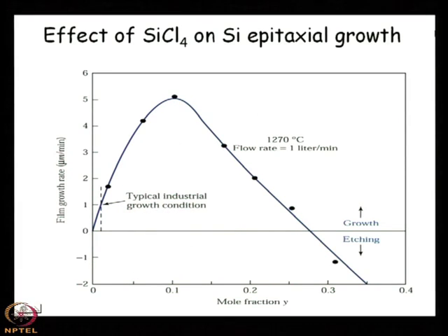So, the costing will be very, very high, because all the material whatever we use, even if we use HCl or H2 gas or N2 gas or SiCl4 gas, it is very, very costly because of its purity level. It is not industrial grade or normal laboratory grade reagent. Okay. So, you have to be very careful about the quantity or the amount of SiCl4 for silicon epitaxial growth.